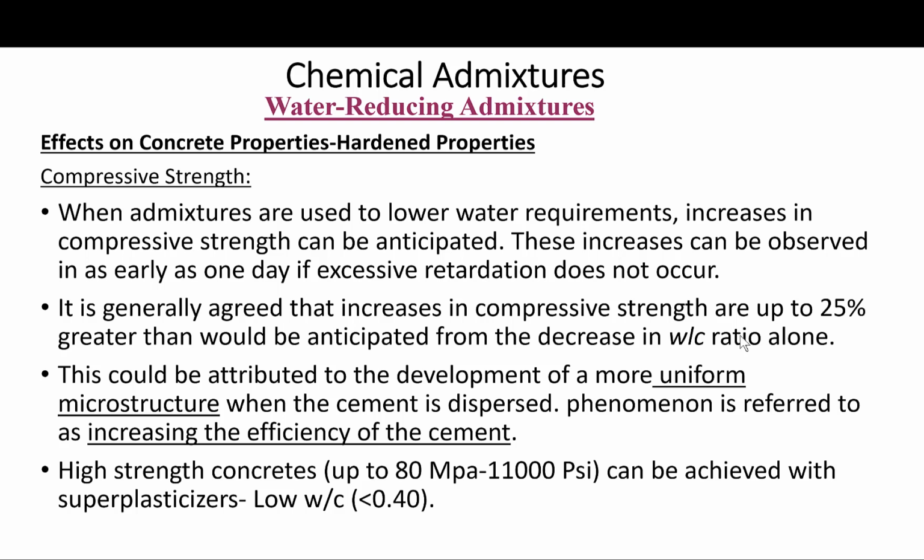So basically, we do not add cement, we maintain the same cement content. What we do is reduce the water content, and eventually we reduce the water cement ratio. Okay, so superplasticizers are well suited to achieve these objectives, and they are used in most concretes with 28 day compressive strength exceeding 80 MPa or 11,000 psi. This only could be done with superplasticizers though.